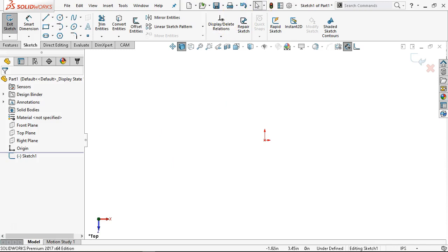Inside of my options up here, there is a checkbox that we're going to get to that says rotate into position when I go into a sketch. So selecting a plane or a face, it'll rotate into that position and put me into that orientation automatically. Now, I'm going to do the Alt and left arrow key and rotate around. It doesn't really matter that I'm upside down and kind of backwards on my origin in particular cases.